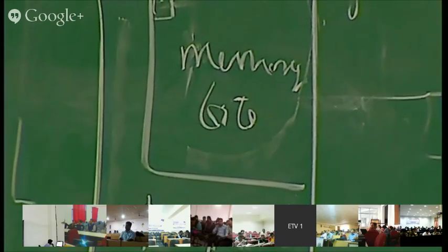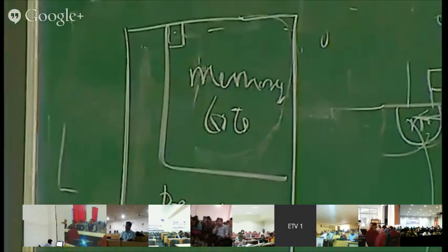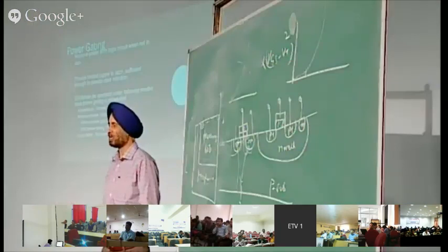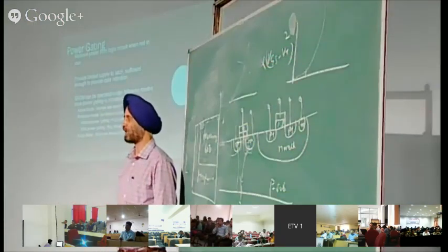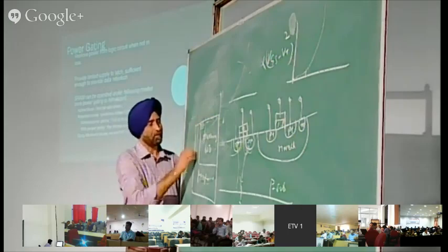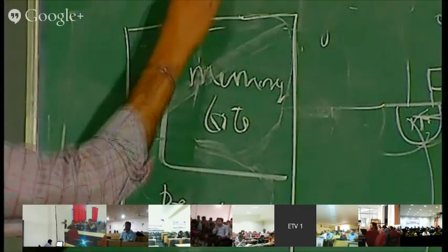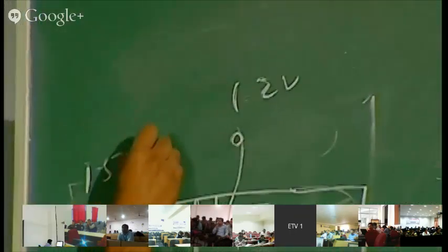Another option is you reduce power to this block also. So there is sleep and deep sleep. Different companies give different names. Deep sleep mode is where the power of the complete block is reduced or shut down. So if the power is at say 1.2 volt, you bring it down to some 150 millivolts.